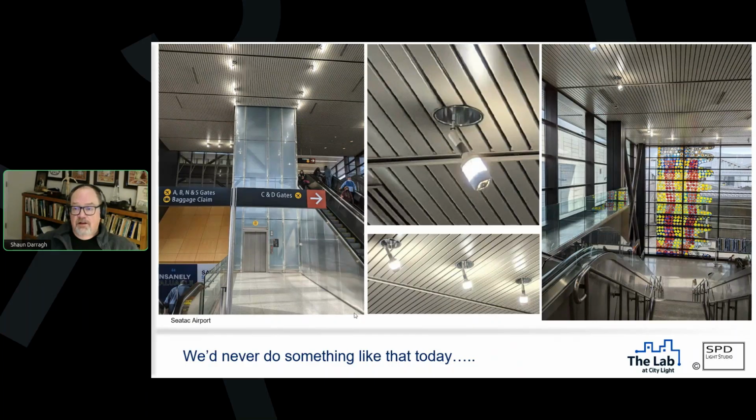A retrofit's been done, I don't know by whom, but effectively what they've done is taken these, we call them corncob kind of LED lamps. I'm sure that the actual lumen package, the amount of light coming out of the bulb itself, is probably pretty high. There's a lot of light coming out of there, but it's not going where we need it. It's not pushing light down to the floor the way that the original design had intended. It's just kind of blobbing a whole bunch of light into the space and hoping for the best. If you've been over there at night, it's absolutely abominable.